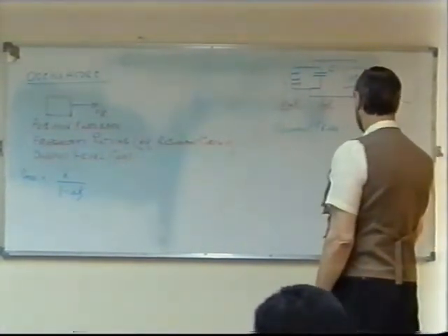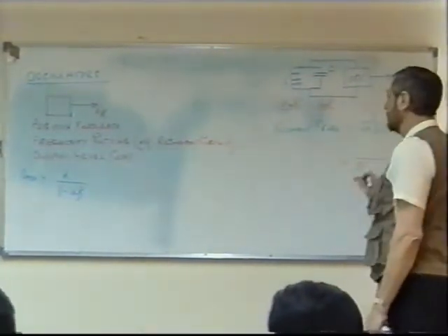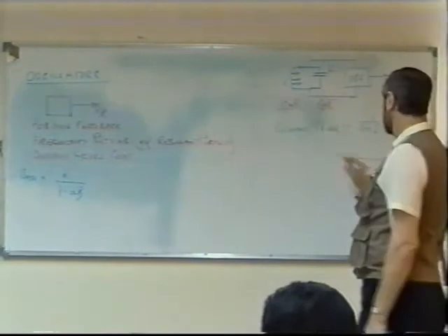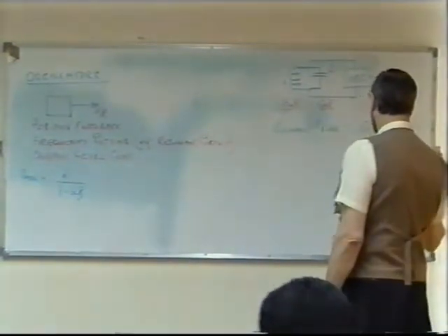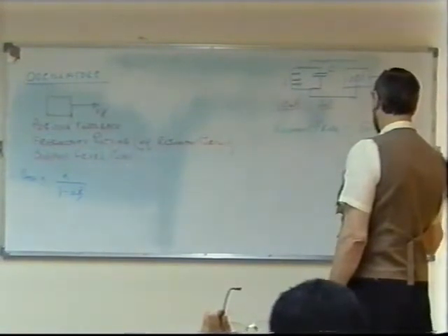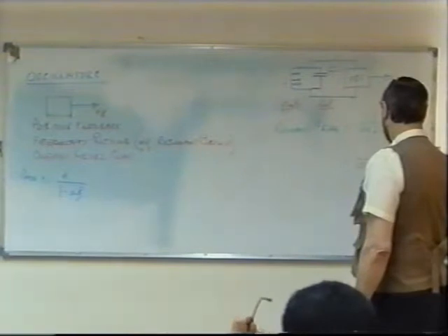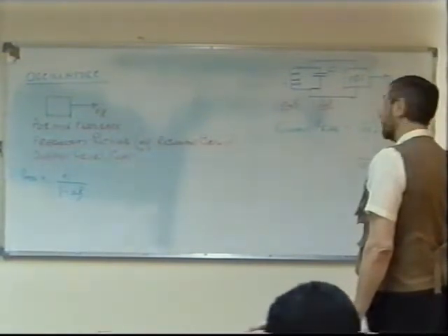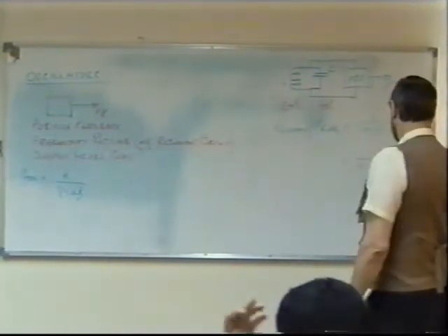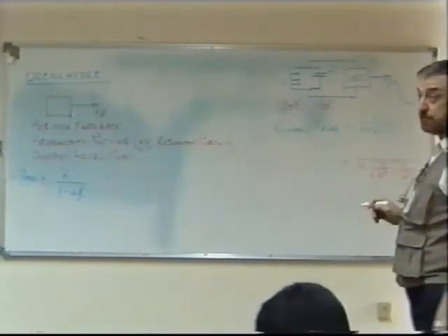But basically, you're multiplying 2 pi and then the root of LC. Now here, of course, we've got 10 milli, so you've got to understand 10 to the power minus 3. It's really 10 over 10 to the power 3, isn't it? And of course, 5 nano is 5 over 10 to the 9. Now there's 2 or 3 ways you can do this.